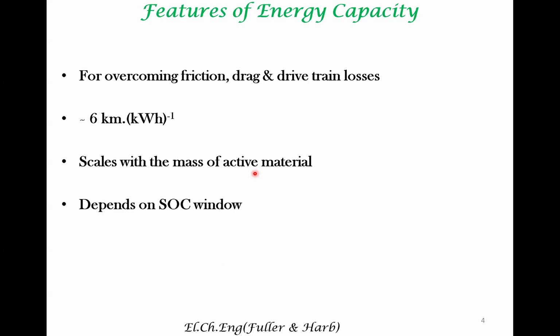Also, the energy that can be delivered by a battery is critically dependent on the SOC window you are going to be operating the battery in. SOC means state of charge. If you discharge the battery to a greater extent, you may be able to get more energy from the battery, but the cycle life of the battery is going to decrease. So it is a trade-off.